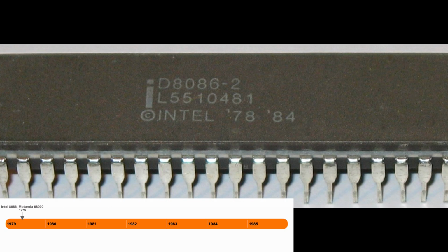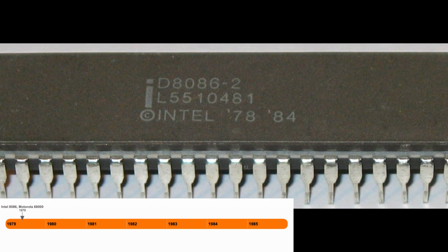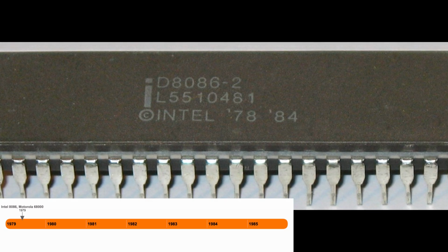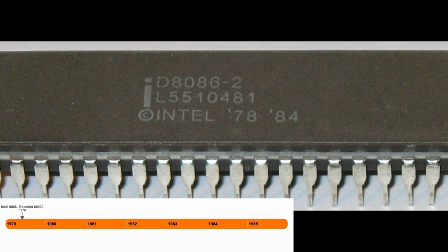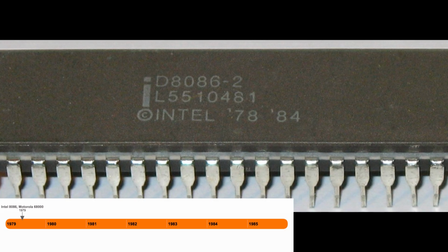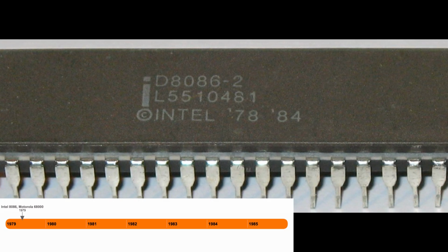It's a good question. It is somewhat similar to a kind of firmware. It is splitting a difficult instruction like dividing two numbers to smaller steps. It is taking more clock cycles, and at the end it has a result. It makes the CPU simpler. That way the designers were able to implement more instructions but still keep the CPU somewhat simple.